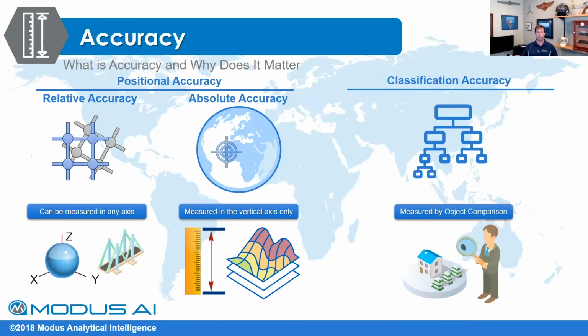And for those that aren't aware, how you do that is you're going to have a series of classification checkpoints, depending on how big your site is. Depending on what your classification scheme is, maybe about 5 to 10 per classification type, so that you can match and say, okay, yes, this is a building, or yes, this is a certain type of low-grade vegetation versus a tree canopy. You'll take a side profile, you may take an over profile, or you may actually use orthographic data to tell you what that is. But that's going to show up in your classification reports, or your accuracy reports.